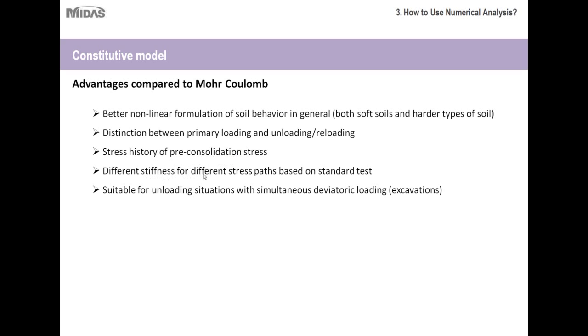Different stiffness for different stress paths based on the standard tests, and it's suitable for unloading situations with simultaneous deviatoric loading, so for excavation. With your excavations, for larger scale excavations anyway, you'll have a lot of loading and unloading, especially if you have construction stage analysis where equipment is being taken in and out, or temporary supports are being put in place. This is particularly useful for simulating that.